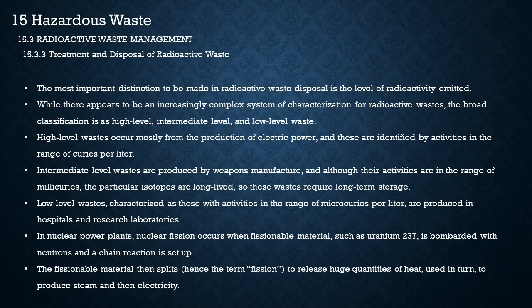15.3.3 Treatment and disposal of radioactive waste. The most important distinction to be made in radioactive waste disposal is the level of radioactivity emitted. While there appears to be an increasingly complex system of characterization for radioactive wastes, the broad classification is as high-level, intermediate-level, and low-level waste. High-level wastes occur mostly from the production of electric power, and these are identified by activities in the range of curies per liter.